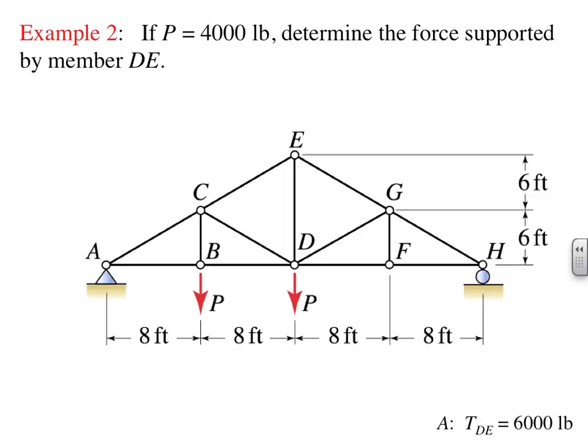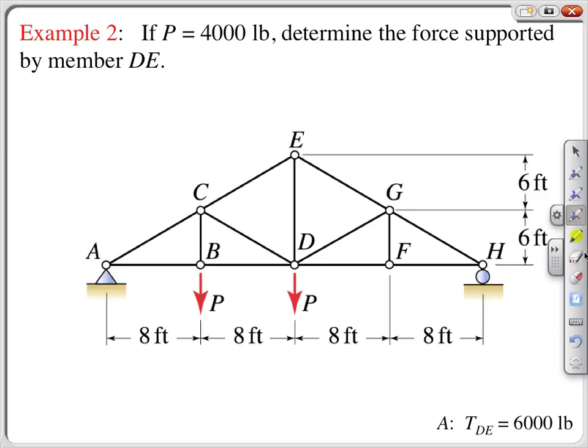For reactions, we count one reaction component for each degree of freedom that's constrained by the truss. A roller counts as 1 degree of freedom, since the only degree of freedom restrained is normal to the surface of the roller.